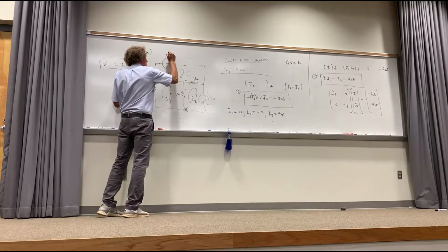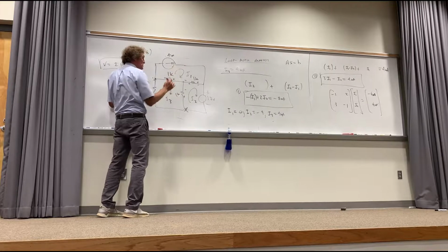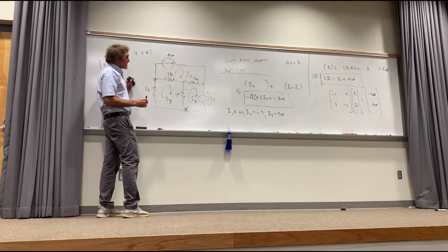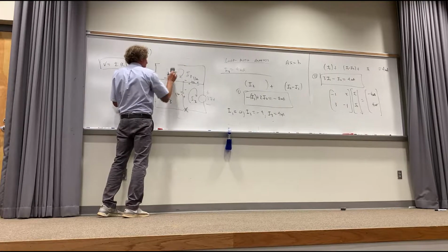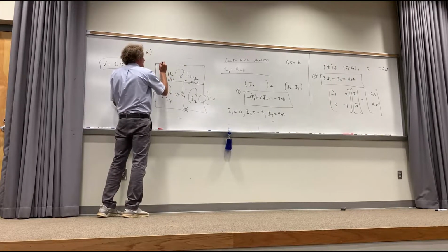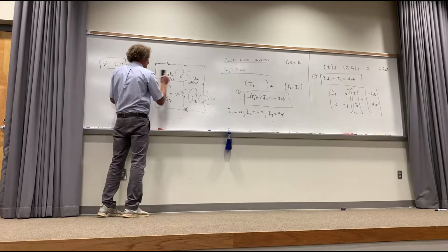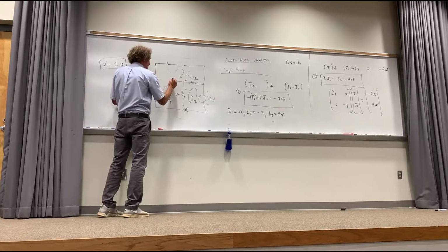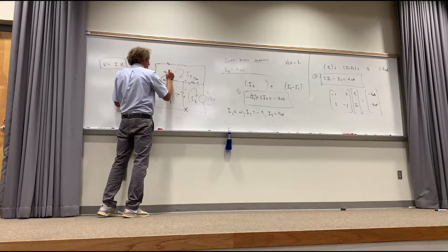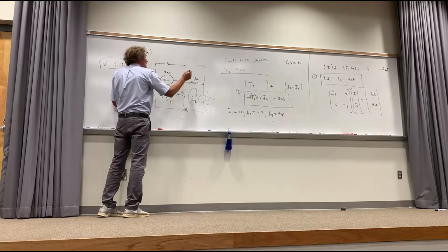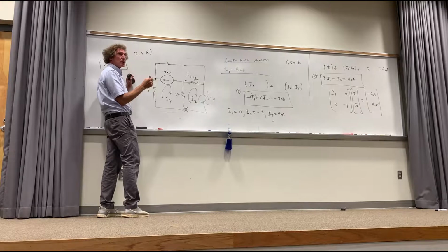I meant the resistor below that, so it's intersecting multiple loops. I meant to replace the resistor that's between I3 and I1, so it's intersecting multiple loops. Right here? Yes. Okay, that's not a problem. Resistor here. Take that out, put in a current supply, right? And let's say this is 4 milliamps, right? So do you have to use nodal analysis then because it splits between I3 and I1?